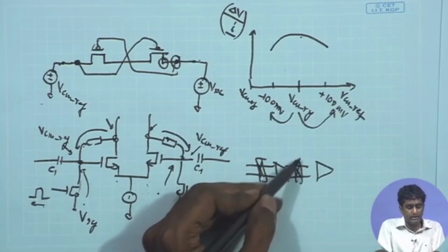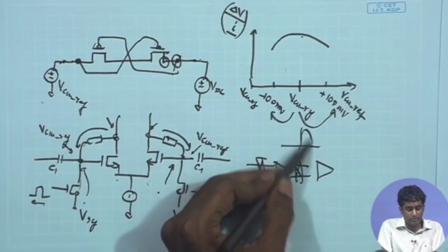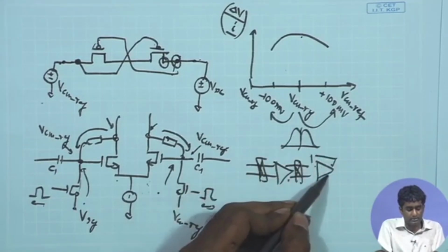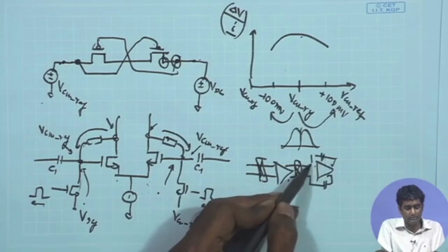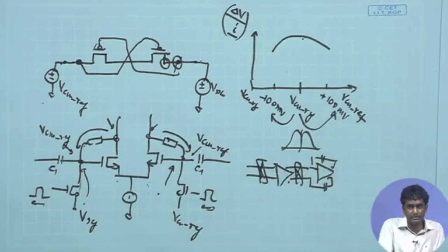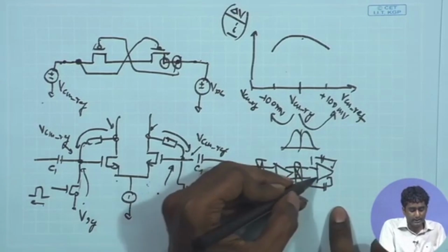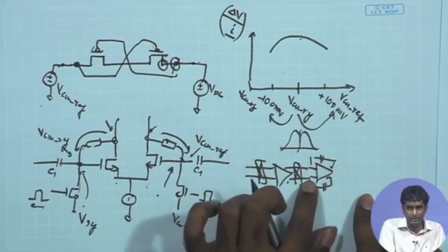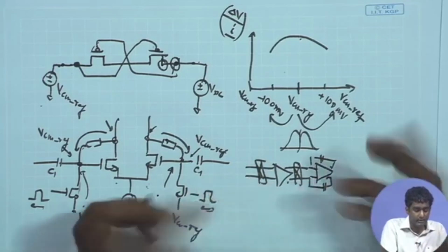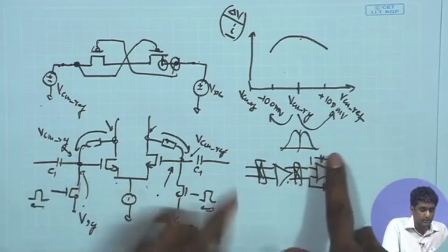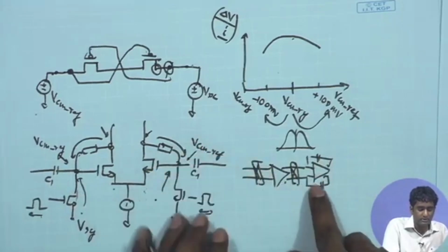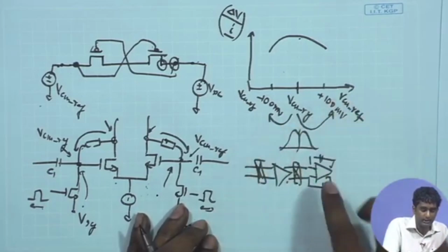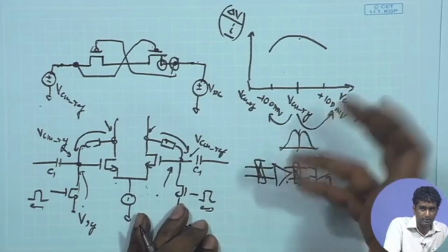After that you have the anti-chopper, and the signal is coming back to the lower frequency, and then the second stage again has that kind of capacitive feedback for further gain, or you have filters made with the help of these capacitor feedbacks and all. So for the second stage amplifier, once again you will need to apply that kind of feedback to settle the input potential at the same point. Since you have anti-chopped the signal and the signal is at low frequency, and you are not applying any chopping over here, once again you may need to take care of the feedback resistor also.